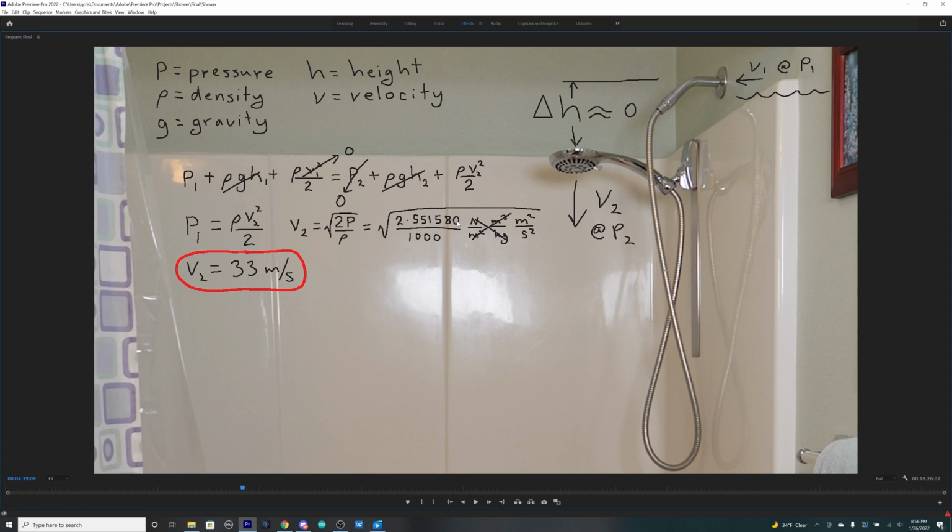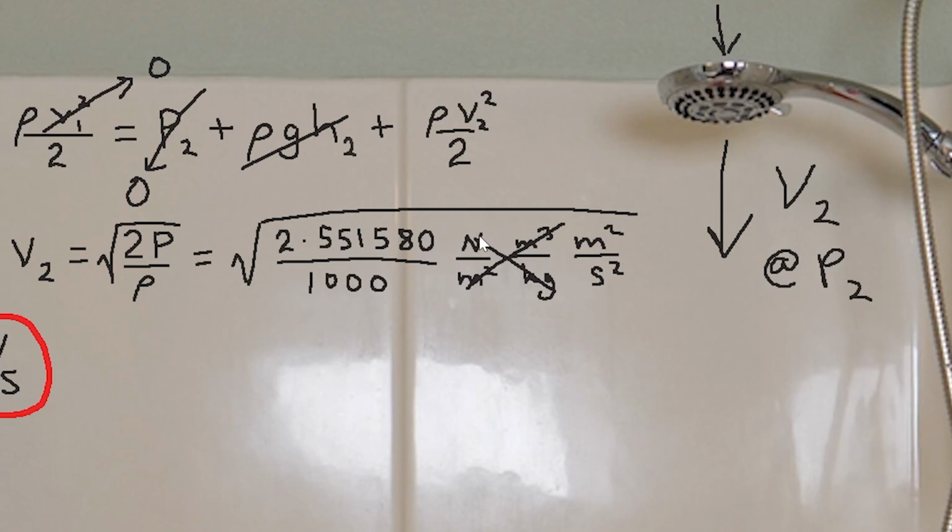But we plug in our pressure in pascals, and our density, I just rounded it off to 1,000 kilograms per meter cubed. And so here is our pascals of newtons per meter squared, and then we've got this density of kilograms per meter cubed gets inverted because it's on the denominator. Dividing by something is the same thing as multiplying by its reciprocal, they used to say. And this is where knowing what a newton is really helps here, because that newton is a kilogram meter per second squared. So we now have a kilogram on top and a kilogram on the bottom. Those go away. We have an extra meter now, so that turns this into meters to the fourth and a meter squared. So the meter squared goes away and leaves us with a meter squared on the top.